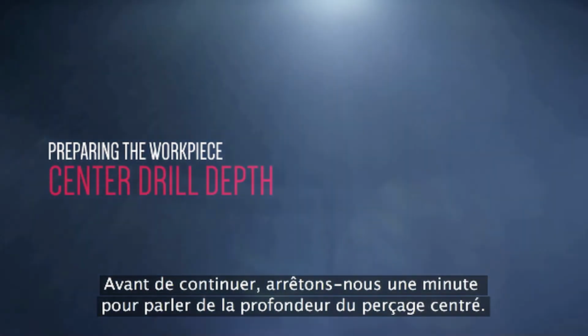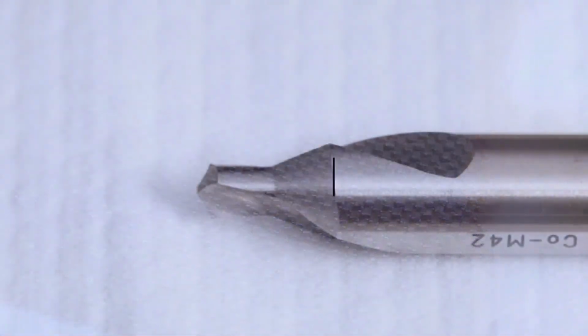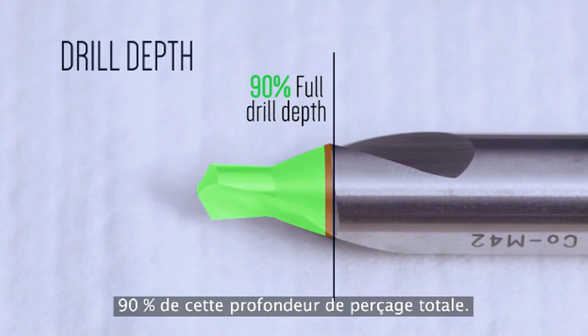Before we move on, let's stop for a minute and talk about center drill depth. We'll look at the important part of the center drill, its 60-degree cutting edge. The highlighted area shows us the full drill depth, but generally, you want to cut into your part up to about 90% of this full drill depth.